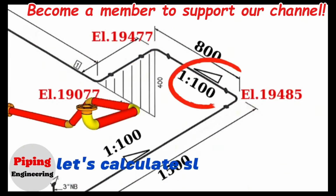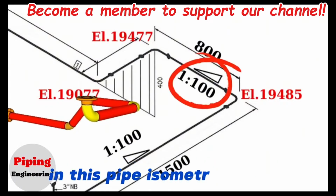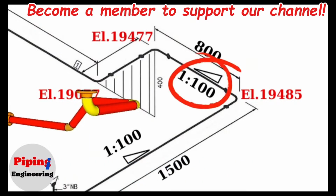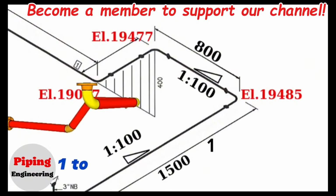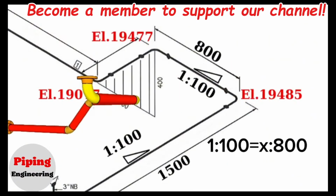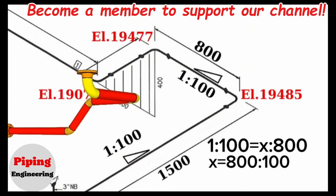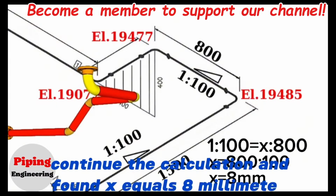Let's calculate the slope ratio now. In this pipe isometric drawing, the slope at a horizontal distance of 800 is expressed as a ratio of 1 to 100. 1 to 100 ratio equals x to 800 ratio. Here x equals 800 over 100. Continuing the calculation, we find x equals 8 millimeters.